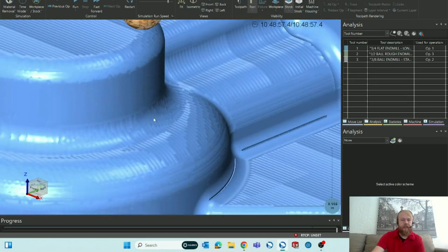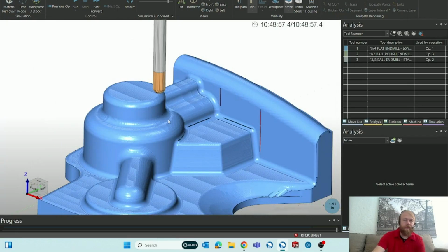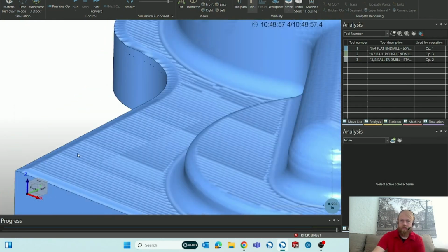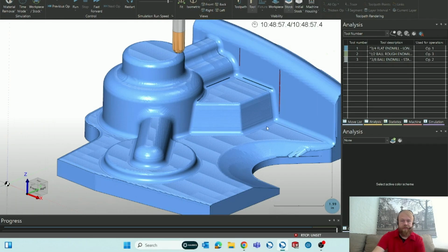So now it looks pretty good. We did a Z-level rough, we did a steep shallow operation, which was the Z-level finish plus planar along any of these flat areas here. And then we did a fillet operation along these areas, along the corners.